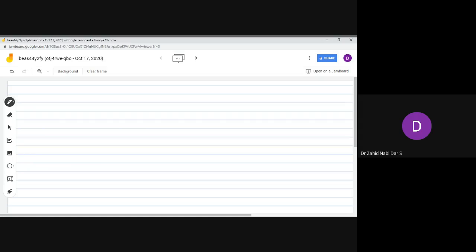Another way of doing it is, if you don't have this much information available with you, you take the transformer loss into account, that is the eddy current plus hysteresis losses, and you equate it to the surface area of the transformer and the heat dissipated area of the tube. So when we are going for the surface area, for example, temperature rise in a plain walled tank.